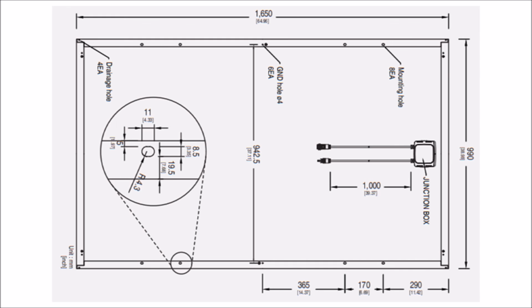Even the information like how much length of cable comes off the back of the module for these MC4 module whips plays a role in advancing solar design, such as how to route the cable underneath the solar panel to make up the extra slack. This is the stuff that solar installers take pride in, having that extra slack tucked out of the way in a workmanlike manner as to not attract nuisances like squirrels or debris.